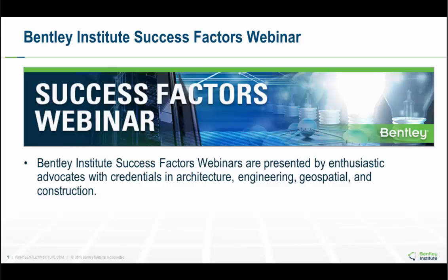Whereas if you run a P delta analysis directly in the analysis, it's a little more hidden. How much did that add? So you have to run it twice, once without P delta and once with P delta, and that of course is also very helpful. So do some experimenting yourself and get comfortable with how much those are impacting the kind of buildings that you design.